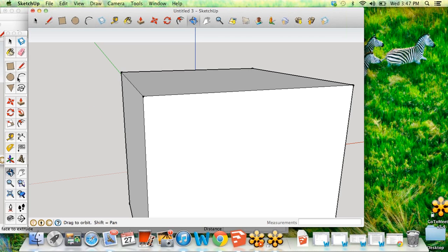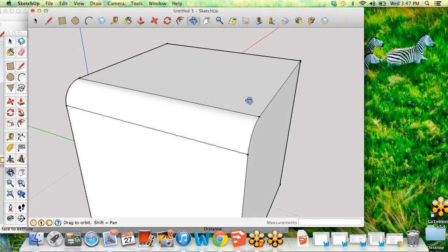All right, so I'm going to show you guys how to do that next step, which is select your arc. Select where on this corner that you want your arc to start. I'm going to select down here, pull it across. So you get that pink line, and then you're going to get that pink tangent. And you're going to use your push-pull tool, select that face above the tangent, and punch it out. And you get that smooth edge.